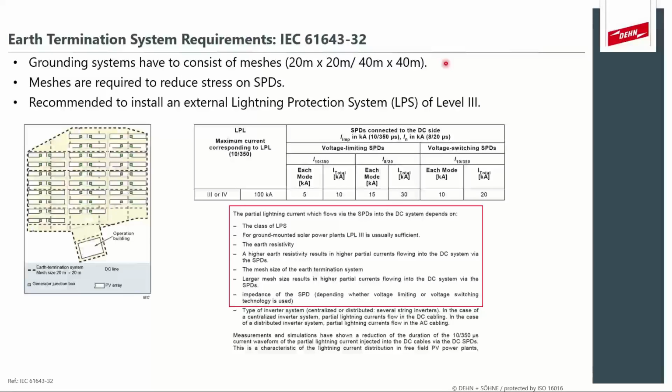Okay, so the meshes are there so that stress is reduced on surge protective devices, so SPDs is surge protective devices, and other equipment within the plant. So all that means is that if there's a lightning strike in this area, for example, the current will split through a bunch of meshes of earthing by the time it gets to electrical equipment. So the energy has been dissipated and attenuated quite a lot, and we don't overstress the surge protective devices that